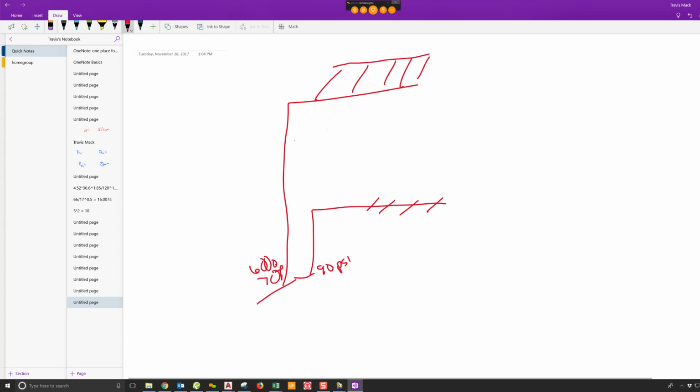So one thing you can do, and this is counterintuitive to what most people think, if they don't understand how calcs work, they're going to just keep opening up pipe sizes, say, oh, well, my 2-inch lines didn't work, let's make them 2.5 so you can handle the over discharge. If I were to shrink this pipe size here, as I had it a 6-inch, if I were to take this to 4-inch, now this 70 may go up to say 89. Okay? Now my pressures are closer to being equal. It's not going to over discharge things. So there are scenarios where making smaller pipe size is actually more beneficial to you than making bigger pipe size.